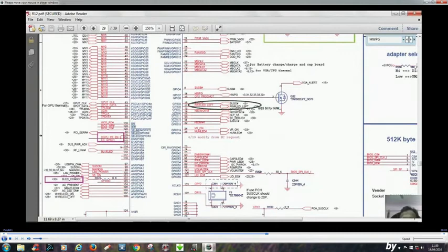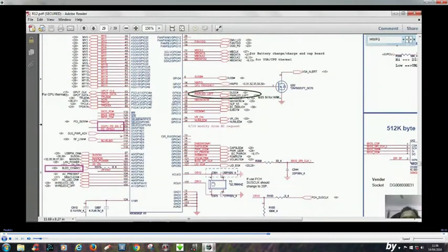the EC_PWR_OK signal, and this is an input to the IO controller, because the IO controller is at the center of power management signals. We have already seen when EC receives SLP_S5, when EC receives SUS B, when EC receives SUS C, then it generates MAIN ON, SUS ON, and VR ON. These open up all the voltages on the main board. So all the voltage regulators will give a hardware power good signal to the IO controller.